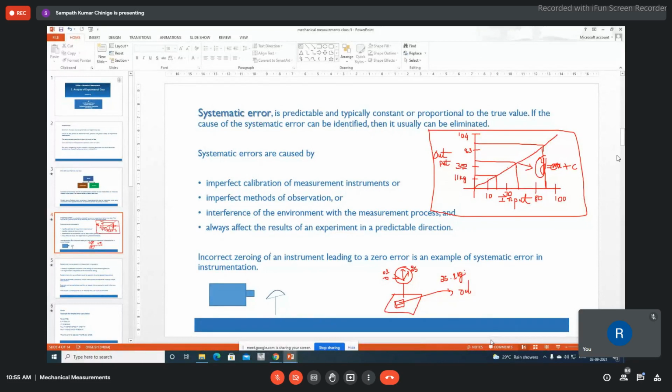You know the precise input and you know the precise output. Likewise, you make similar measurements, and then you know the equation. This expression, the calibration equation, you will give as an input to the data acquisition system, and it will record. Now, whenever you want to measure any system, the same thermocouple, when you put it over here, gives an output. Internally, the data acquisition system will put that value into this equation and finally display the X value. So that is how the instrumentation and the experimentation will be done.